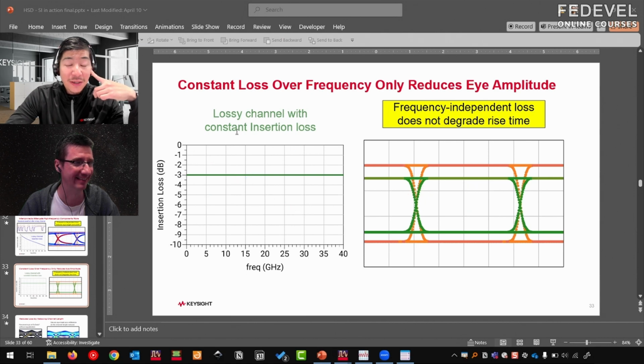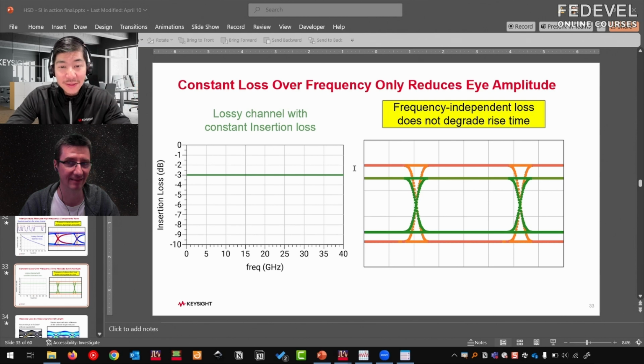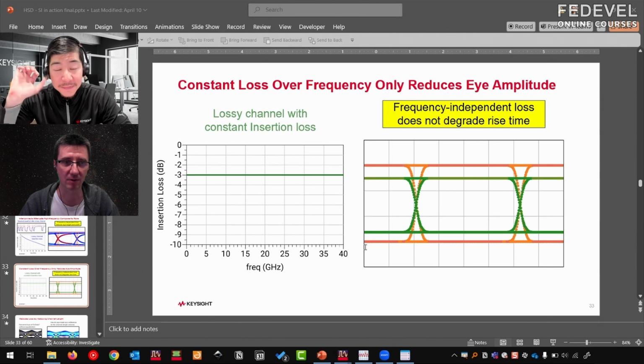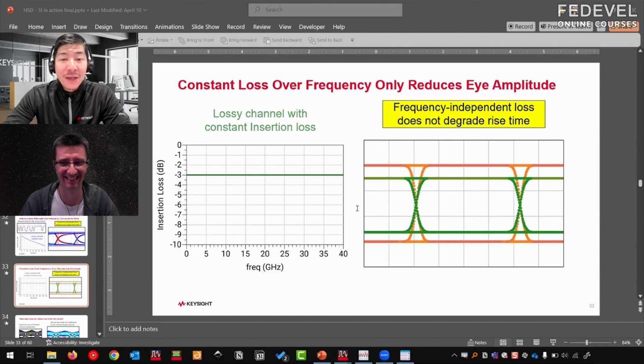And that's why we want to do equalization, how we fix the signal. We can correct the signal. But when you are setting up these equalization parameters, you need to know this loss graph exactly, no? Oh, yes. A lot of times, the technical term would be the back channel. The transmitter needs to know what the channel looks like before it can do some correction. That's a good observation.